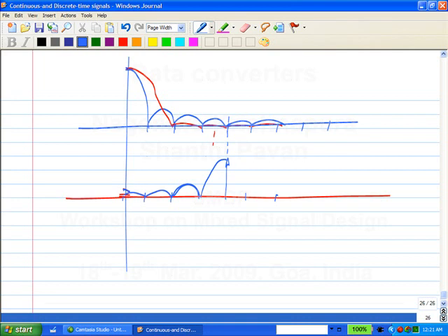And when I sample it, I will get 1 here, 0, 0, not 1, n by 2 here, 0, 0, 0 and so on. Okay. So in fact, when the frequency is accurately set, I will get the ideal result with the rectangular window. What will I get with the Hann window? Okay. I will get this and this. And after that everything will be 0.